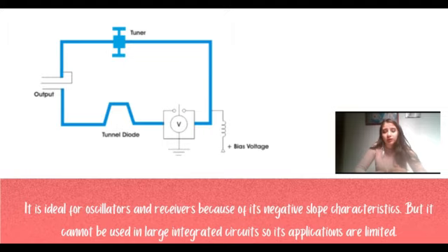Tunnel diode oscillators are intended to operate at microwave frequency. They generally use some form of transmission line as a tuned circuit. These oscillators are useful in applications that require a few milliwatts of power, for example, local oscillators for a superheterodyne microwave receiver.